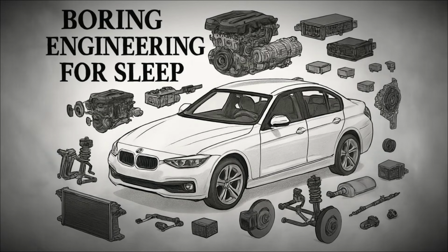A shock absorber is a hydraulic cylinder filled with oil or gas, and as it compresses or extends, it forces fluid through valves, dissipating energy as heat. This controlled resistance prevents the car from oscillating and ensures that after a bump, the wheel quickly returns to stable contact with the road. Modern cars often use struts, which combine a shock absorber and a coil spring into one compact unit, saving space and reducing weight.